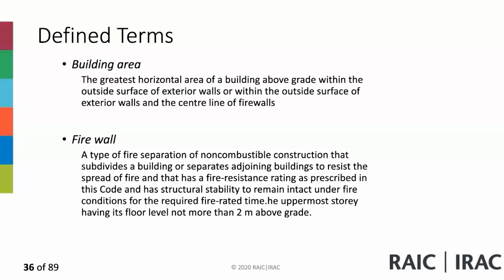Building area, the greatest horizontal area of a building above grade within the outside surface of exterior walls and center line of firewalls. So different buildings are divided by firewalls, so you can look at them individually. And then the building area of each can be measured from exterior wall to exterior wall, or if you have buildings separated by a firewall, from exterior wall to a firewall. And I'll show you a picture on the building area.